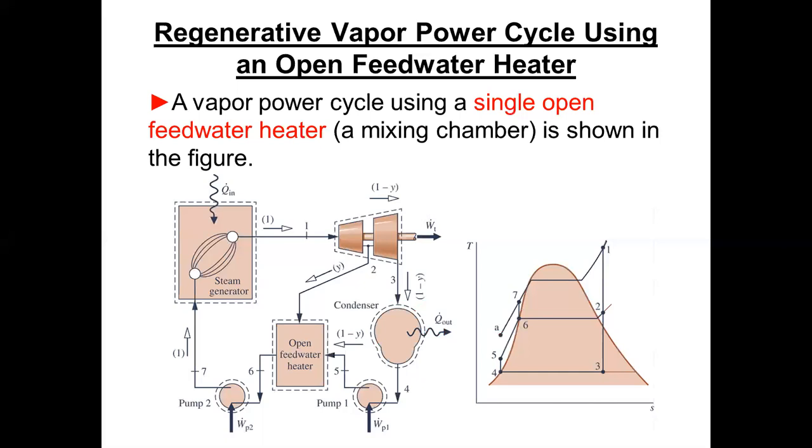But as far as controlling the corrosion levels in the cycle, it's critical. So you've got to have that. We call it the DA, for deaerator vent, that comes out. Some cycles throw that away. Other cycles will put it in a heat exchanger or take it someplace to retain the energy in the cycle, and then somehow you've got to get the air, nitrogen, or whatever came out, vented. And so all that mixes together, and we come out at 6, and then we go into another pump.